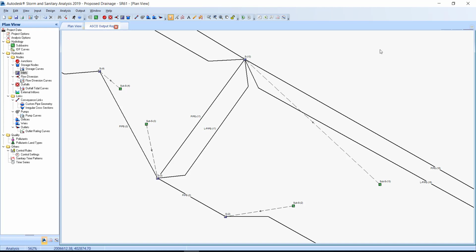If you find that the oscillation continues at the upstream node while the connected downstream pipe is surcharged, then define a ponded area at the downstream connected node. This can sometimes eliminate the oscillation at the upstream node and produce a more stable model.